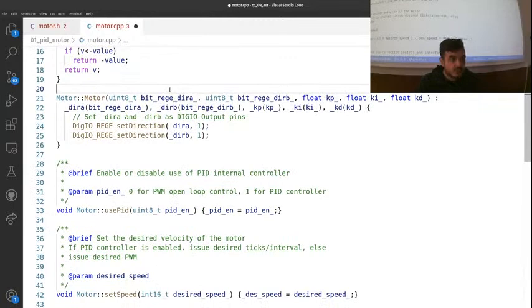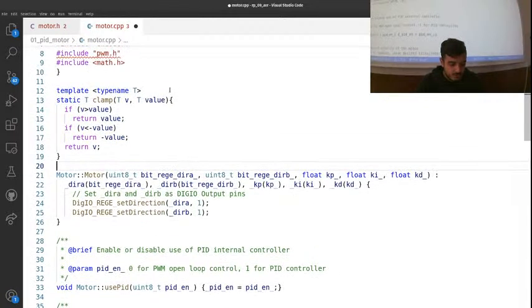In the construction, what is this clamp method that you have on top? Actually, we added a clamp function for you to use, which is useful to limit a variable inside a specific, symmetrical range. It's mostly used to bound the errors or other components of the PID, but also for the velocity input that must be given to the motor.